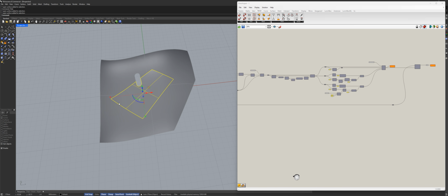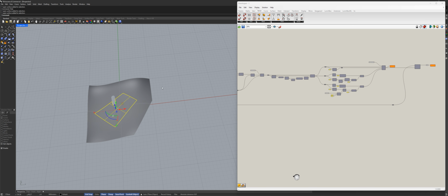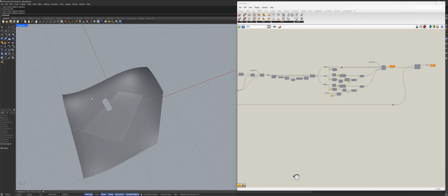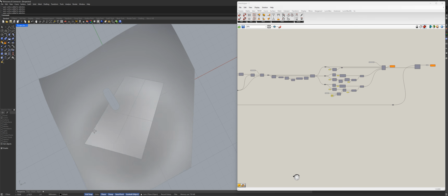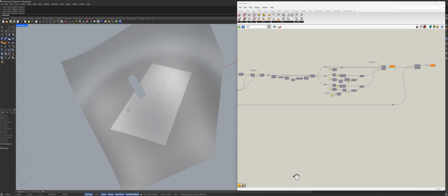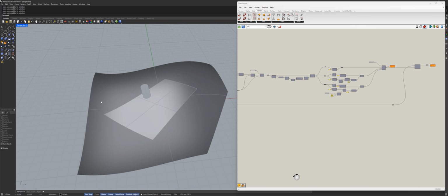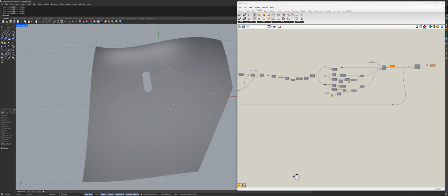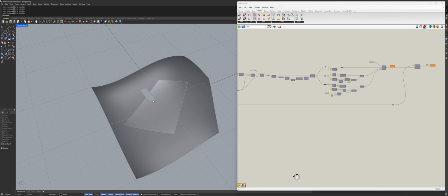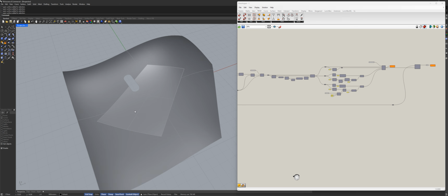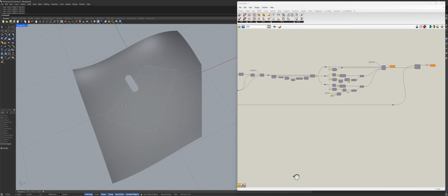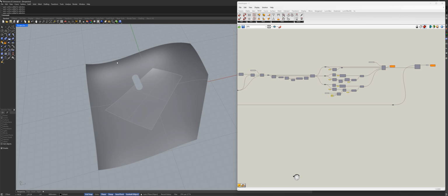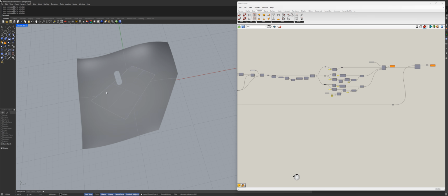So in the previous lessons we worked on a single surface. Today we need to work across multiple ones. Now let's look at that a little bit closer. First of all, they are two independent surfaces, and if you look at the shading, it's quite noticeable that the shading is different. But that doesn't mean that these surfaces are not perfectly flowing. They are continuous. The nuance here is with the importing itself, because when you're importing from other programs, it can take slightly different colors and parameters for the tessellation for different kinds of surfaces. So this is not an issue.